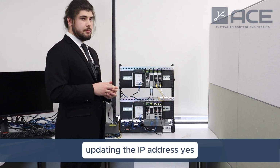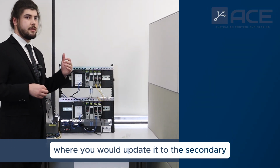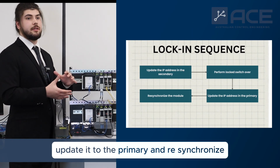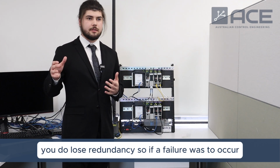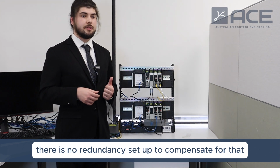Updating the IP address, yes, you would need to have a locked sequence where you would update it on the secondary and then perform that switchover, update it on the primary, and then resynchronize. But the important note is that when you do that, you do lose redundancy. So if a failure was to occur, there is no redundant setup to compensate for that.